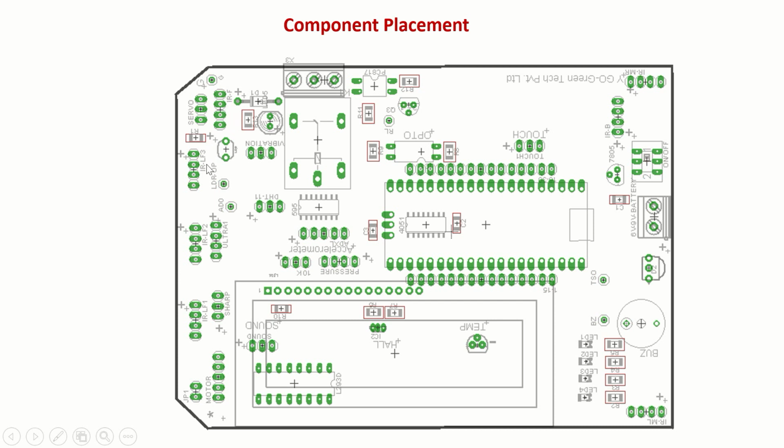Otherwise, you have the infrared sensors like I already mentioned: IRF1 here, IRLF3, LF2, LF1. On the back side of the PCB, IRB, IRM, then IRML. So these are also sensors where you can connect. However, the moment you say IR, we actually used a multiplexer, the CD4051. This is the digital IC which takes care of selecting any one of these IR sensors as the output, which is connected to microcontroller pin number 2, that is IO36.